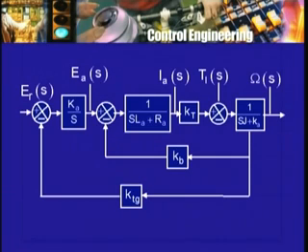From that the back EMF is subtracted, which gives rise to a voltage that essentially drives the current through the armature inductance and resistance combination. So there is this block 1 by SLa plus Ra that gives rise to the armature current. Kt times that is the motor torque. From that subtract the load torque. The difference is the torque available for overcoming friction and acceleration. That, going through a transfer function 1 by Sj plus Kf, produces the output quantity, namely omega S. This is the complete system.